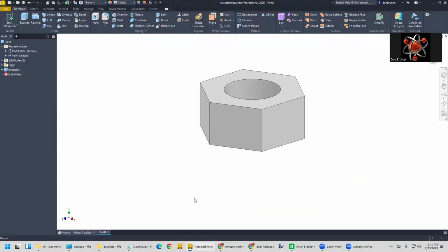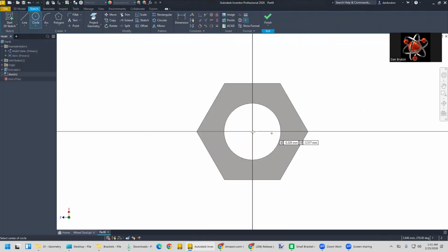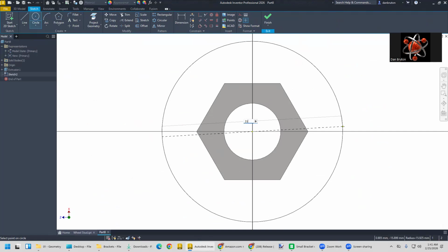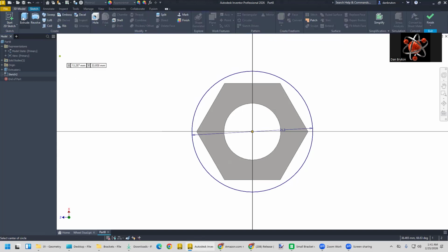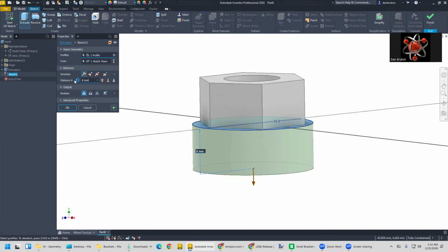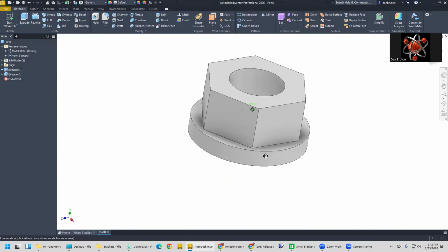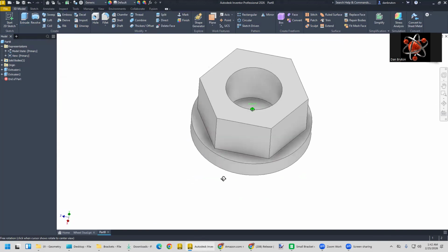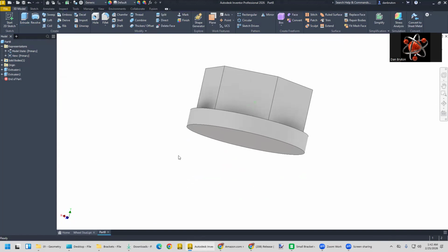Right. And I'm back. So we will go to the bottom face, I suppose, and start a new sketch there. And this is where we're going to put in that distance I just measured, up 21.3 millimeters. And we know the thickness of it was about 3. So we'll go to 3D model, extrude. This shape right here, we want to keep going down with it like that, but only 3, like this. That actually looks a bit too much also. But that's what I measured, so we'll go with that.